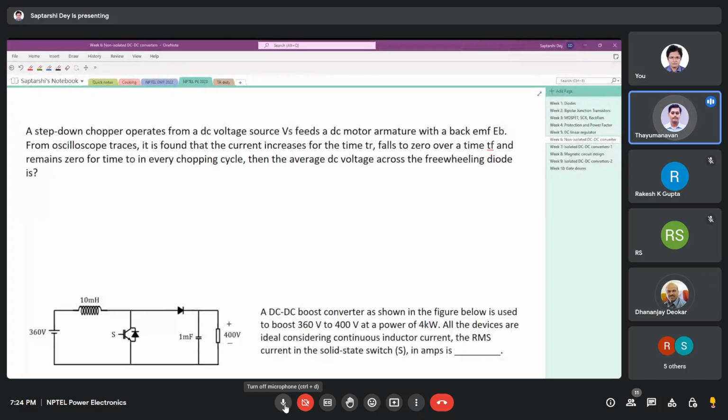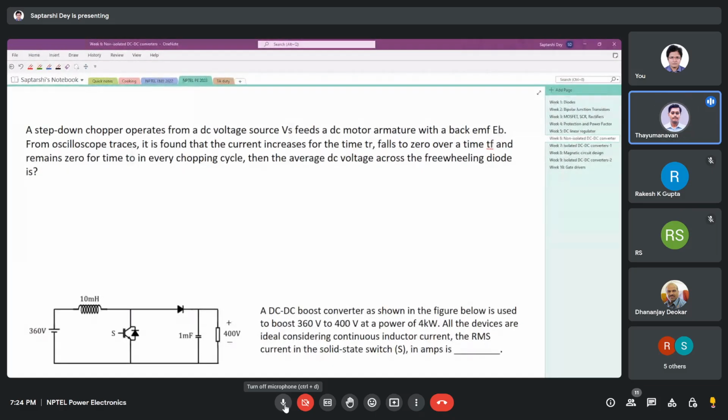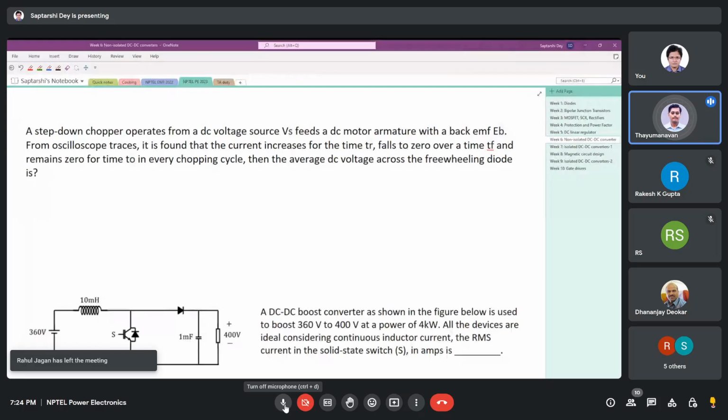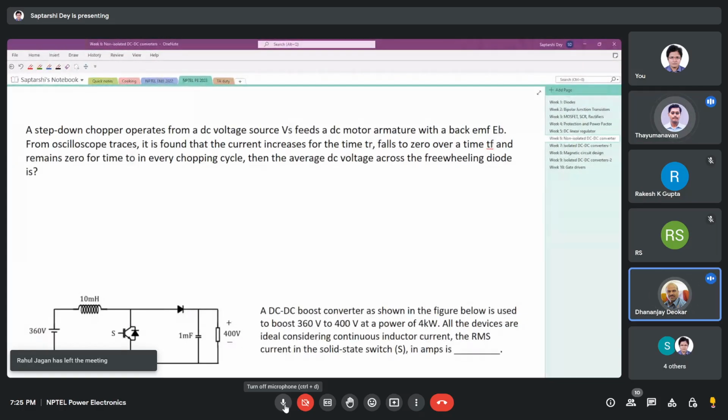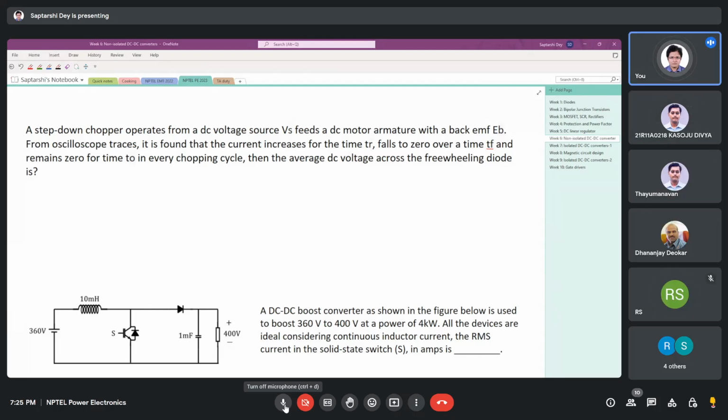From the given values, the duty ratio seems to come out as 1.7. For a buck boost converter, sir explained that it has 3 ranges of D. For buck operation 0 to 0.5. If you are getting a duty ratio more than 1, you must be doing something wrong.